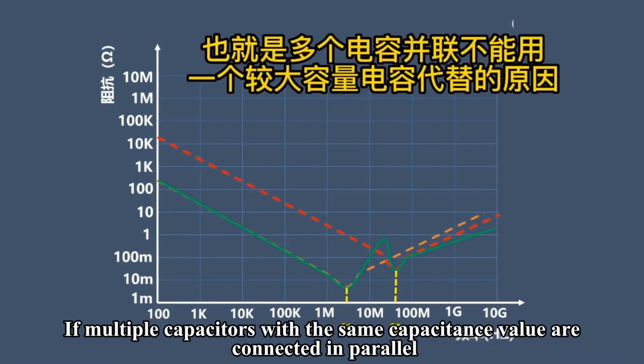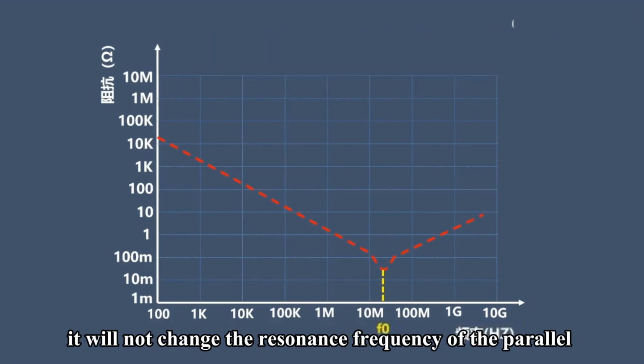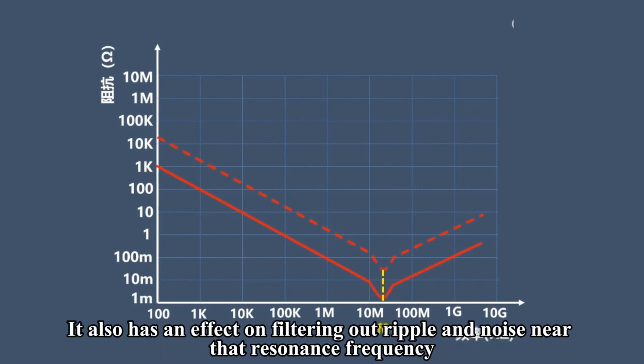If multiple capacitors with the same capacitance value are connected in parallel, it will not change the resonance frequency of the parallel capacitors but will reduce the overall impedance of the capacitors. It is equivalent to multiple capacitors connected in parallel and reducing their equivalent resistance. It also has an effect on filtering out ripple and noise near that resonance frequency.